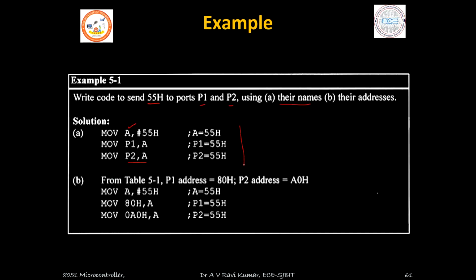Here, instead, I can directly write MOV P1, #55H, and similarly MOV P2, #55H. This is also an instruction to move the values to port 1.